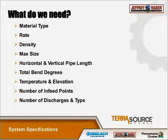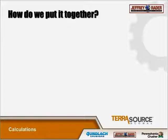If you've got a diverter valve that splits the run into two, typically the longest pipe run is going to be what's critical, because it's going to be, as we say, the worst case scenario, but we would like to look at all the piping runs to make sure that the shorter run doesn't have, say, a larger vertical section or more elbows, which would actually turn out to be the worst case scenario. And then the type of discharge is, of course, important, because there's going to be different pressure losses associated with each different type. So how do we put this together?